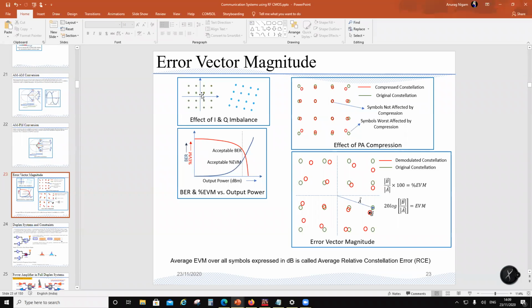Okay, so if I take this as a phasor representation, then every bin has a unique amplitude and phase, which represents a certain symbol of 4 bits. So when I'm transmitting, I'm just transmitting that. Now there is a problem with this. The problem is phase information and amplitude information are way apart. So the best way to do this is to take the polar representation of amplitude and angle and split it up into 2 rectangular components. One would be called the I component, which will be this one. One will be called the Q component, this one.